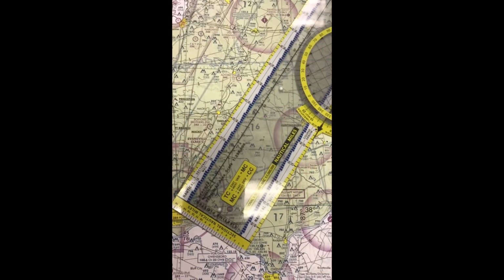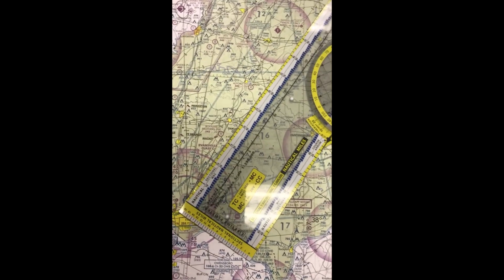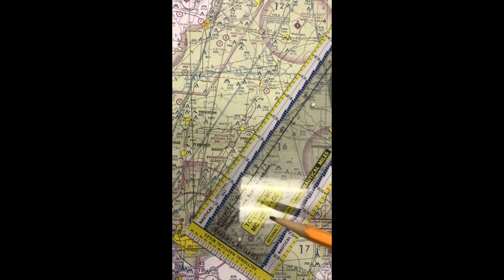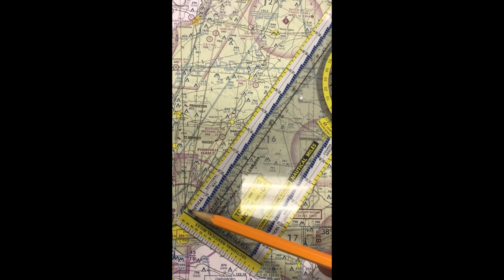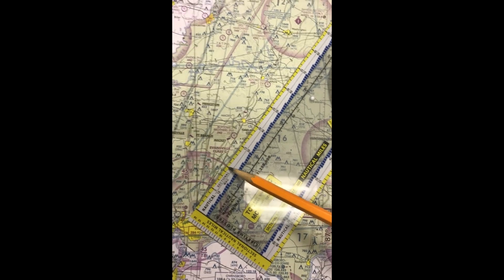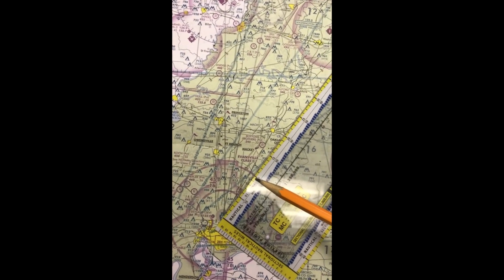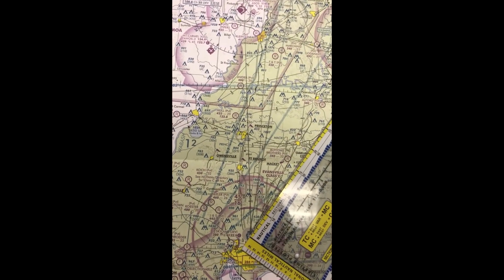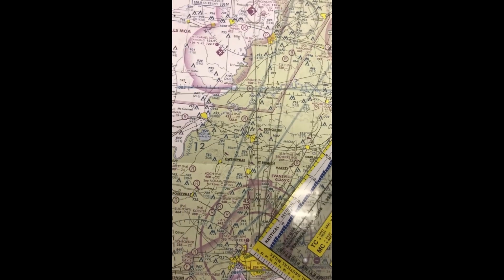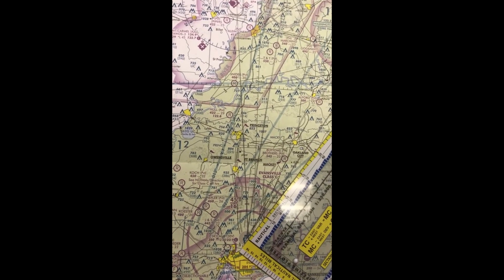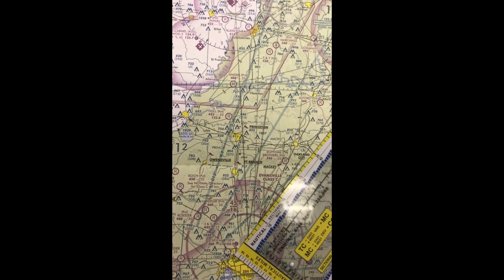Now, you recall from that time, speed, and distance to climb, we said it is going to take us 10 nautical miles to climb. So using the sectional chart scale on the plotter, we park our reference there, and at 10 nautical miles, that's where we're going to reach our cruise altitude. Now, keep in mind, even when we're climbing, we're still going to have to start navigating. We're still going to have to start looking for checkpoints and landmarks here. So what we can do is find a prominent landmark that's approximately along our route of flight and find out where that's going to be about 10 nautical miles.